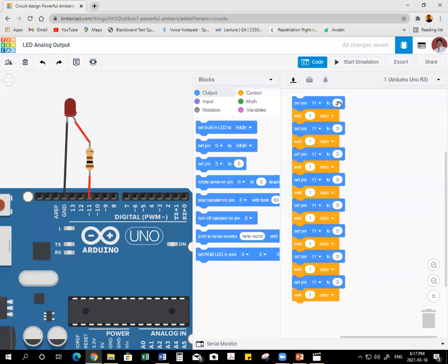It's wasting time. So set pin 11 to 0, and another 1 second I will wait, and set pin to 50, and for another 1 second wait, another is 100. Next wait another 1 second and 150, and wait and another 200. Now again wait, and maximum I will go now 255. Okay, this is one step.